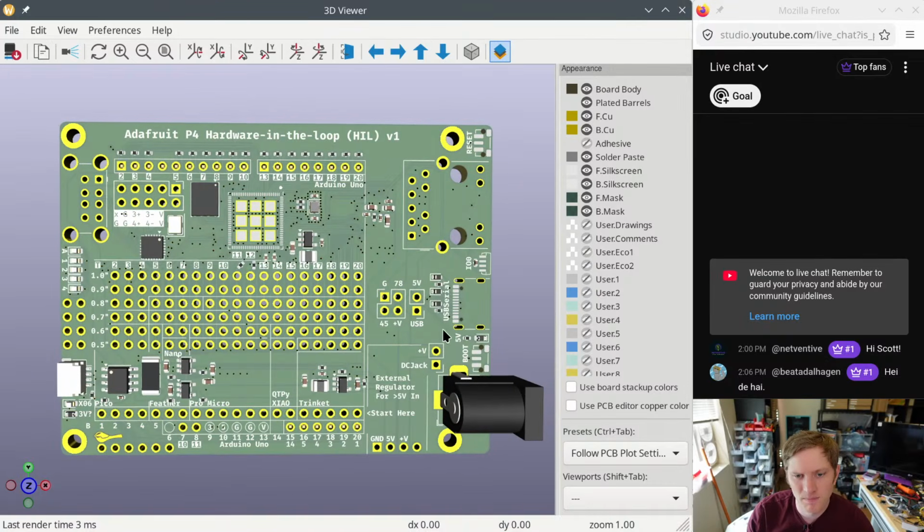The first one to start with is just USB power. There's a header here to connect the USB power to the 5 volts in, and then that 5 volts goes down here to get 3.3, and then these are two switches for 3.3 and 5. They then go through this INA290, I forget what it is, a current sensing thing, so it can tell you the current through this giant resistor, and that power then goes up this way to the USB headers. So the switched power is the USB hub, and the USB hub takes 3.3 and 5, and then 5 volts goes out the two USB headers here.